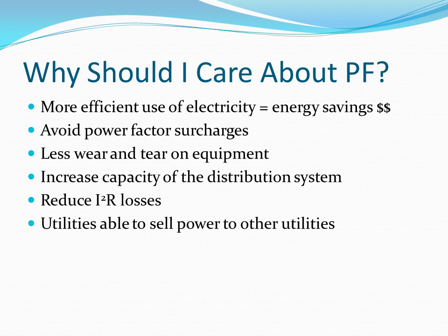Generally, loads such as lighting ballasts, motors, fans, and computers do not have a good power factor. As a project manager or consultant, improving power factor will lead to a more efficient use of electricity within your system or distribution grid. A more efficient system leads to cost savings in the form of avoiding power factor surcharges, less wear and tear on equipment, lower maintenance costs, and less frequent failures. It also provides an increased capacity of the distribution system, as well as reducing line losses and increasing voltage stability.